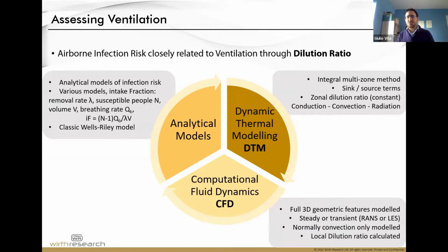Actually, these three methods kind of do the same thing, but they also do very different things. First, we have analytical methods. They are based on assuming constant parameters for your room, normally a single room, and they are extremely well known in the industry. They're used to have an idea of the general early risk level of your design.